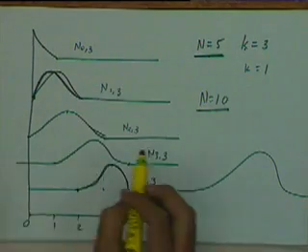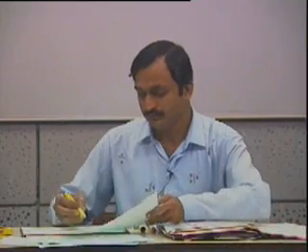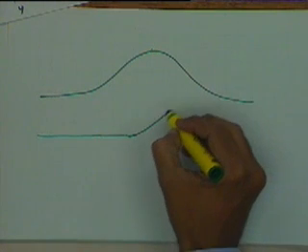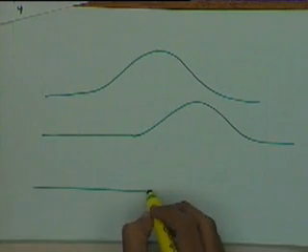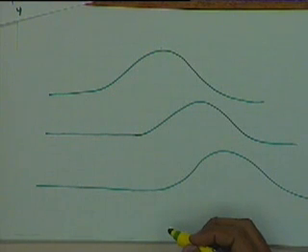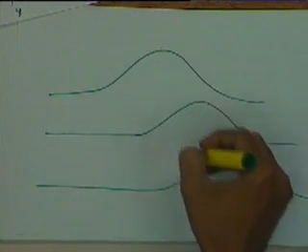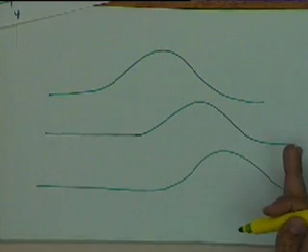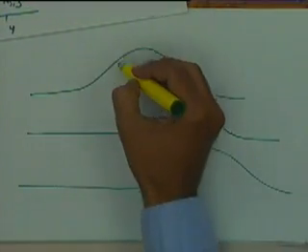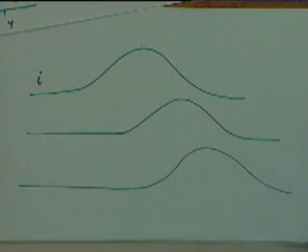So if we consider a portion where, let's say, we have many points, we have one shape function like this. The shape function for the next point is going to be staggered and will be like this, and the shape function for the next point will again be staggered and will be like this. This is how we will get 3 successive shape functions, or blending functions. We should use the term blending functions. So the 3 successive blending functions will look like this, except at the ends. So except at the ends, we can write an expression for the curve in terms of these general shape functions. I can have, let's say, i points on this side, and I can have any number of points beyond this.